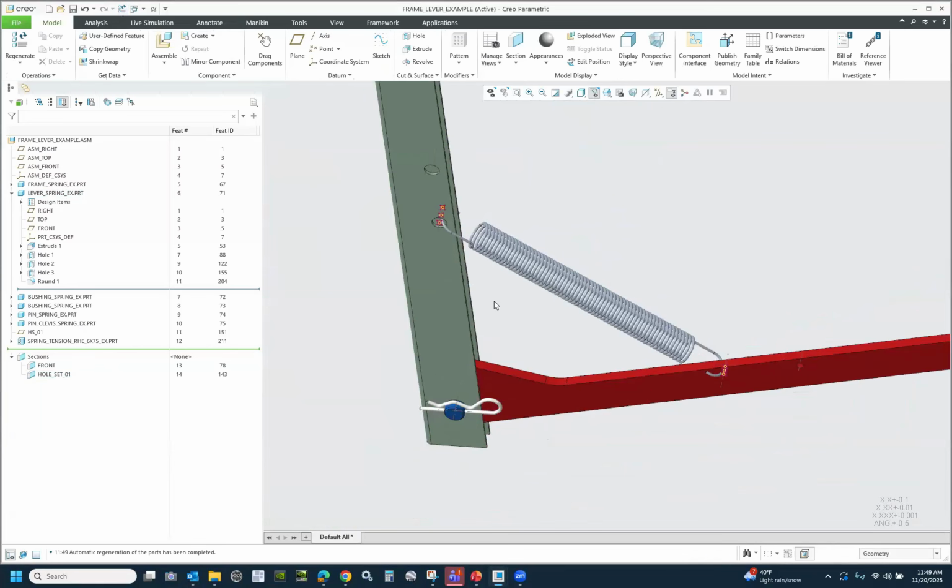If I put that very same spring into this other set of holes, it'd be longer in the assembly, but it would still be the same spring as far as my bill of materials is concerned. All right, and that's what I want. I want accuracy in my bill of materials. I also want accuracy in my assembly. So for a lot of parts, we have to think a little bit differently about how they get modeled and then how they're used in the assembly.